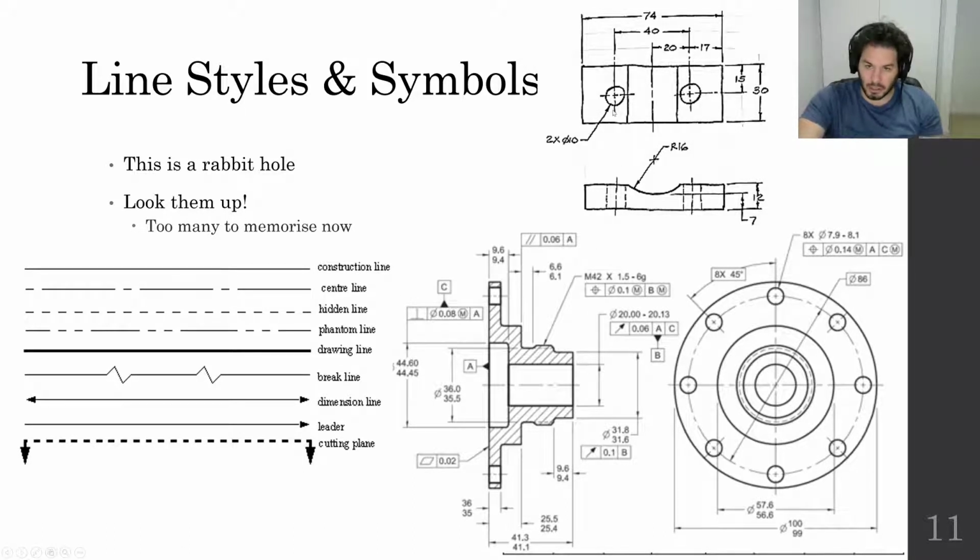I did miss hidden lines. Didn't speak about that. So hidden lines are things that basically, if you had some form of X-ray vision, you would effectively be able to see these holes that are punched in the top of this object. So they've been drawn in here basically to just tell you that this hole goes all the way through the object out the other end, that it is in fact a full hole. The reason why they're used here is that this top view itself doesn't necessarily tell you that these holes go all the way through. They could come down and just sort of end halfway. And if they did, this top view would look identical. But these hidden lines would look different. So hidden lines can be used to show that type of geometry, or a section can be used.